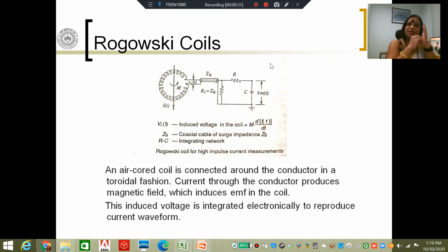When PD happens, we would like to know the magnitude of the PD that is taking place. So we would like to detect the PD. That is the first thing that we need to do. And no doubt about it, that is an important achievement and an important objective. However, if you need to take corrective action, it is not enough, especially when you're dealing with power equipment, which can be very large, which can span over a large area. It is most of the time not sufficient to just be able to detect the presence of PD. In fact, most of the time you will have PD.